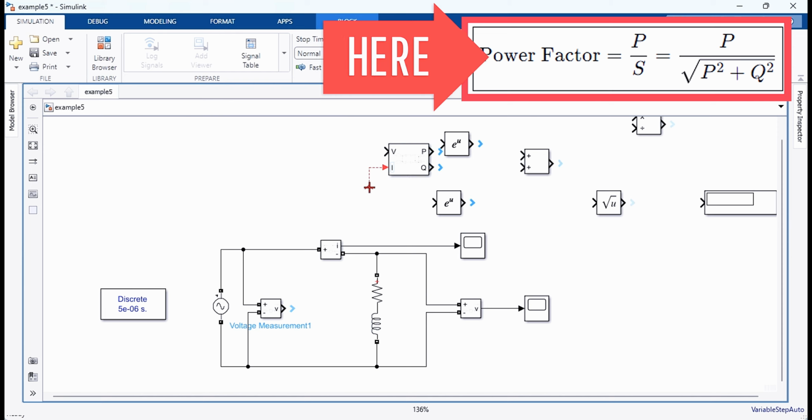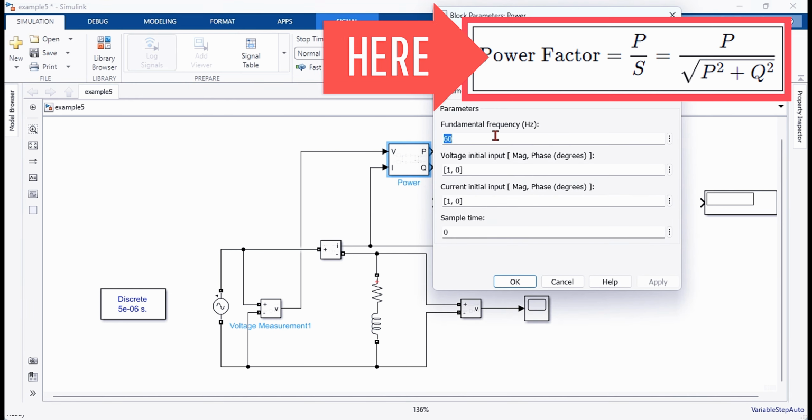Connect the input I of the power block to the output of the current measurement block, and the input V of the power block to the output of the voltage measurement block. Double-click the power block. Set the frequency to 50 Hz. Click OK.